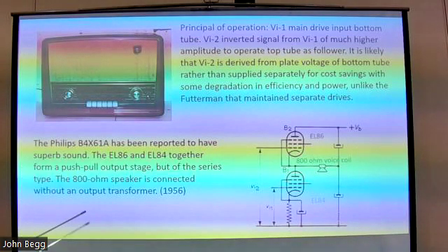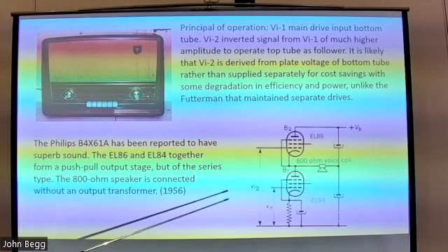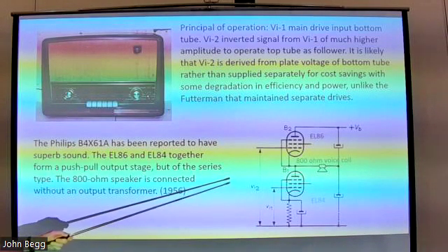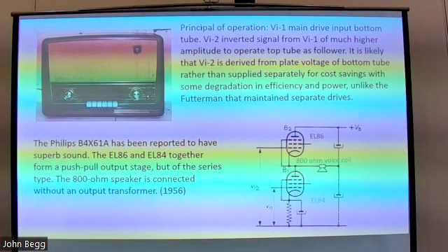Philips came up with the idea, well, let's make an 800 ohm speaker. So they made this radio, made a couple radios, and a friend of mine told me they made a TV set with this too, but they had the speaker split between the high side drive and low side drive tubes. And so that was their solution to making an OTL amplifier without having a ridiculous number of tubes in parallel. Next slide.